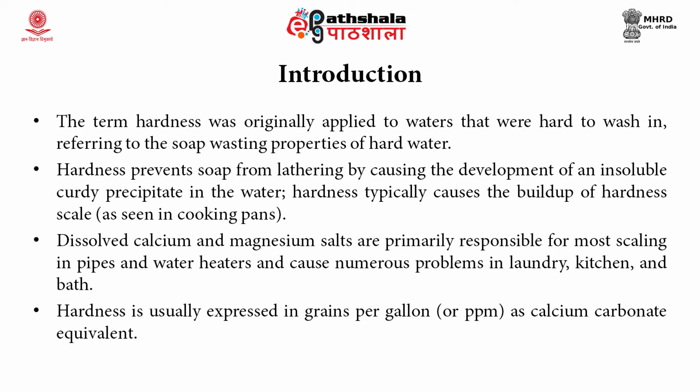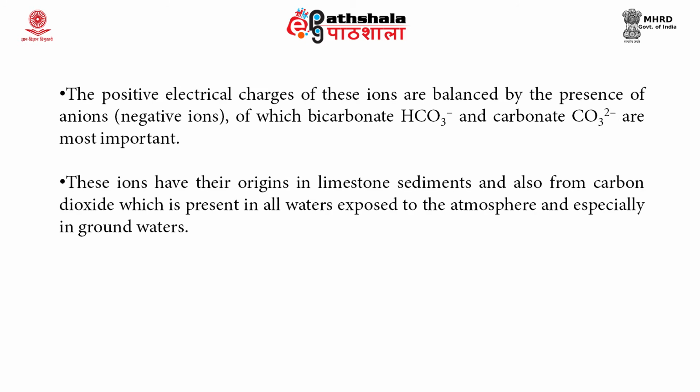The hardness of water is caused mainly by the salts of calcium, magnesium and the anions bicarbonates, chlorides, sulfates and nitrates. The positive electric charges of these cations are balanced by the presence of the negative anions, and these ions have their origin from the sediments or the rocks with which the groundwater comes into contact, and the carbonates which are present in the water are a result of the contact of carbon dioxide, which is present in all waters which are exposed to the atmosphere.